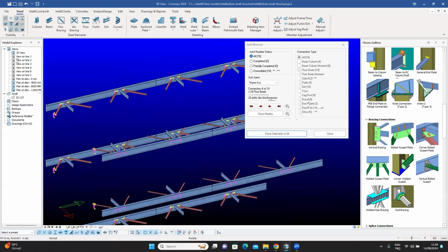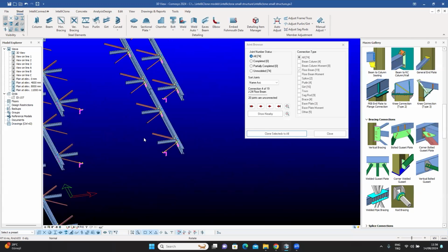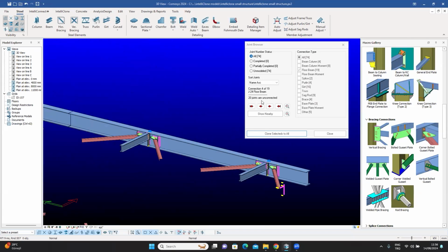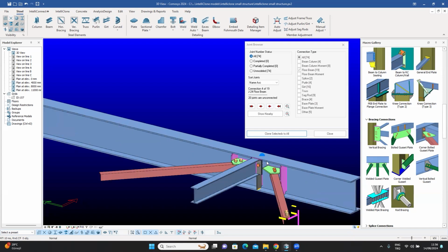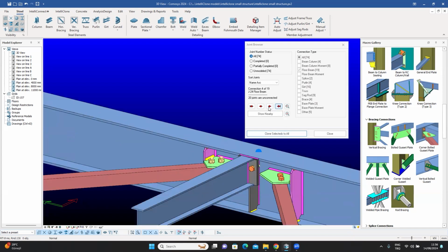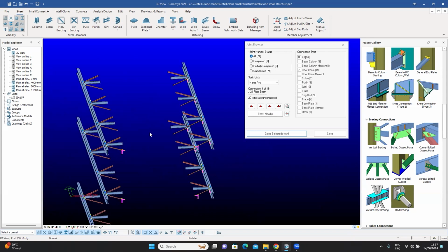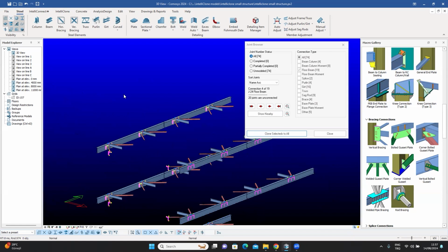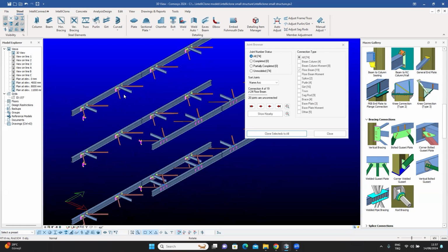This is extremely powerful because this really reduces my work almost 20 times. If you notice, if I'm going to finish this building by just pressing the arrow key, make one connection, say clone, then basically by pressing the arrow key 19 times, I have connected maybe hundreds of joints. So this is a unique way of modeling your building, a very different way of modeling your building. And this is what this does.